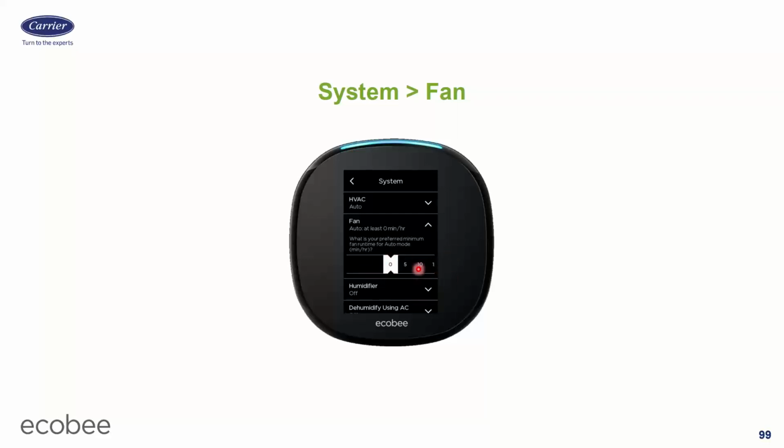The reasons you would do this are, 1, code compliance. If you have an outside air ventilation intake duct and you need it to be running X amount of minutes to get the ventilation air that you have, that's a whole other discussion we could talk about separately. But you could do that here. Or maybe they got some really nice indoor air quality air purifier. They got a Bryant Evolution air purifier or a Respicare or whatever it is. And you want to make sure that you have the fan running, because if the fan's not running, then it's basically not sending anything into my house. So what's the point?